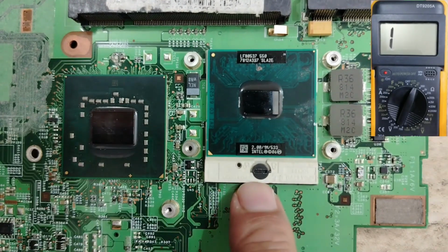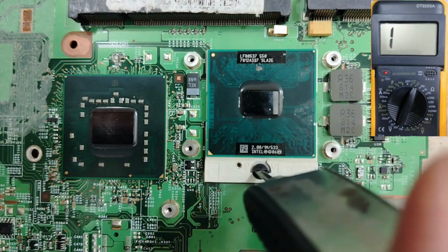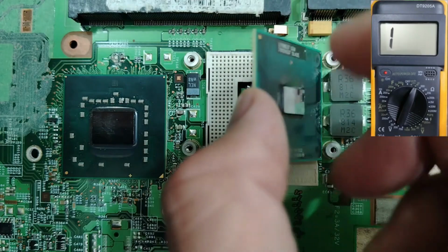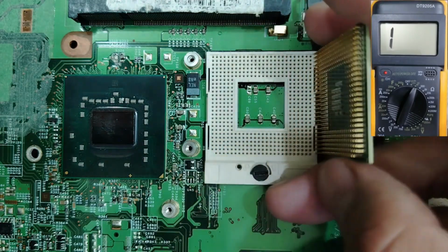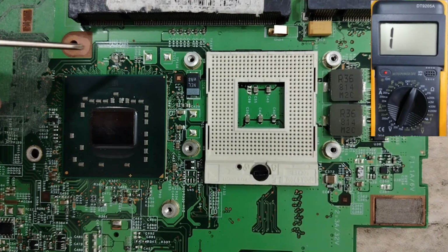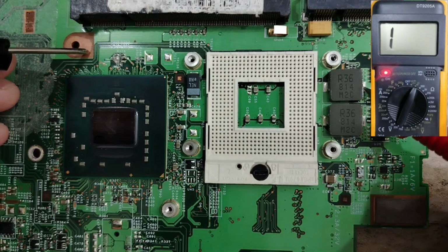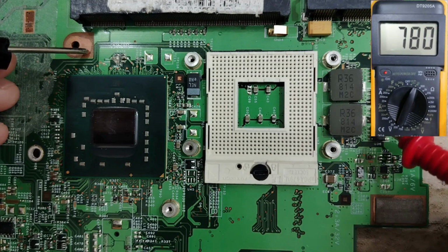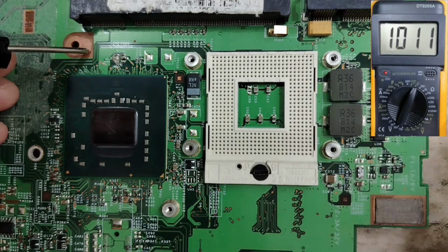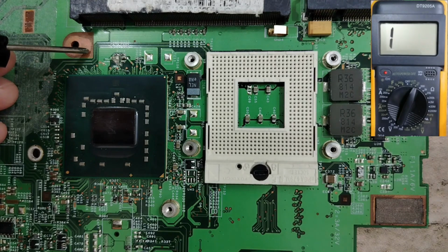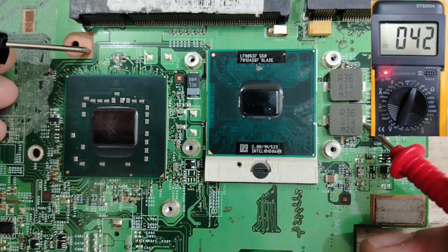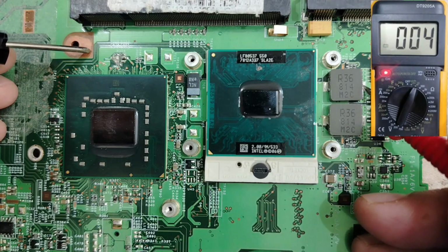So let me remove the CPU. So let's unscrew the CPU like this, as you can see. So let's now remove the CPU, as you can see. You see, the CPU is removed. Let's check again. So the black probe in the ground here, and check this inductor. Do you see in the multimeter? We get a high read. Means this is not a short circuit. Okay? If we put back the CPU, as you can see, let's check. Back. We have a low reading.